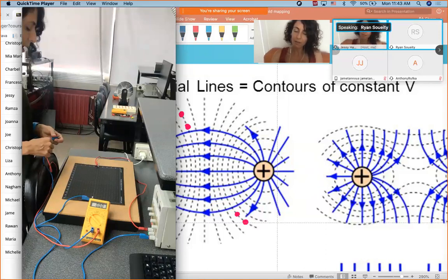But does it matter which one, if the red or the blue? Well, no. It doesn't matter because I'm finding the zeros. Let's say I want to find a potential difference that is positive 2. This is where I have to monitor all the polarities. Since in this experiment, I only need to find the 0, I don't really care about plus and minus. And you see throughout the procedure, I've never looked where's my plus and where's my minus. Okay, because my job was to find the 0. Positive 0 or a negative 0 doesn't really matter. But usually we take the negative terminals to be references. So the other one would give you a positive answer.